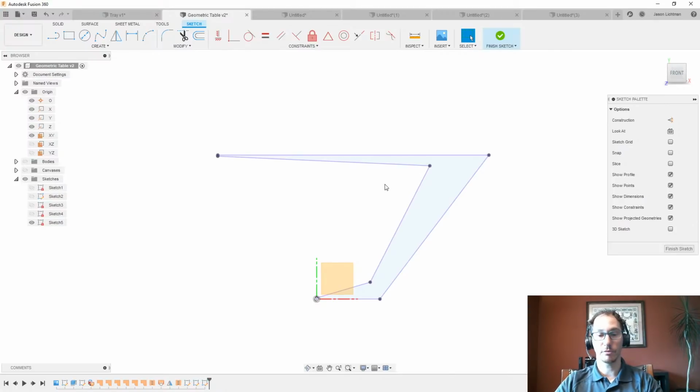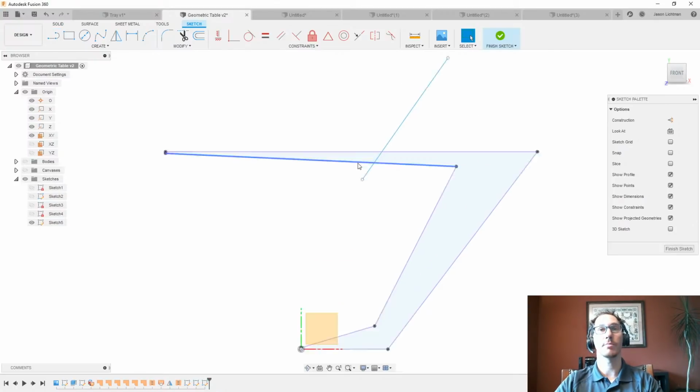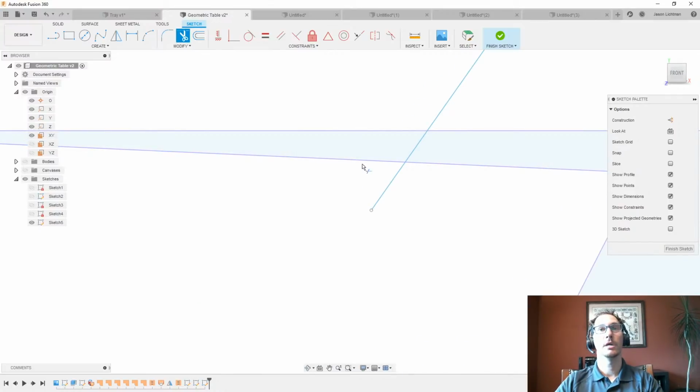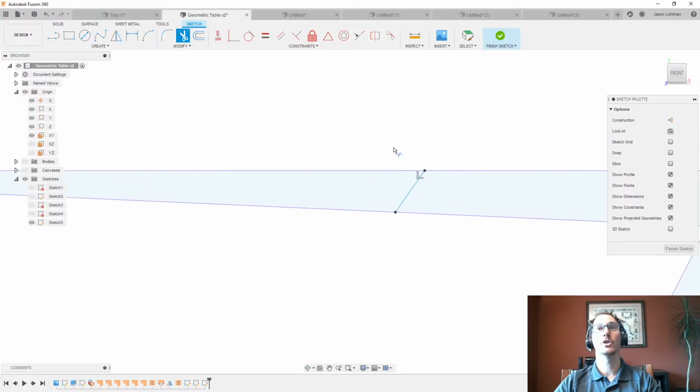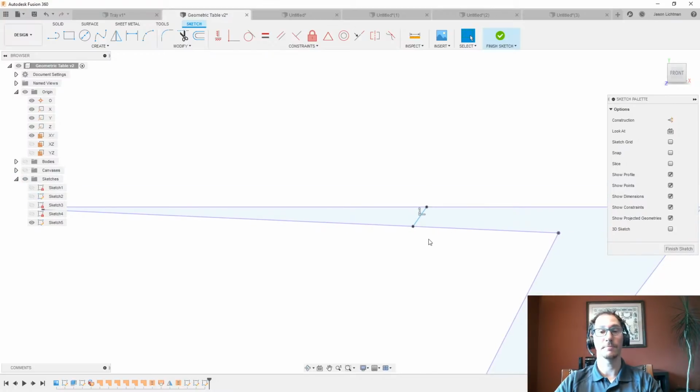So if I end up drawing a line that goes across this table and I want to trim this particular magenta line, it's not actually going to let me do it. Will it let me trim the new geometry that I create around it? Absolutely. So I can trim this edge, and now I have a line that just goes across the magenta areas, but I cannot trim the magenta line. So keep that in mind, that's really important.